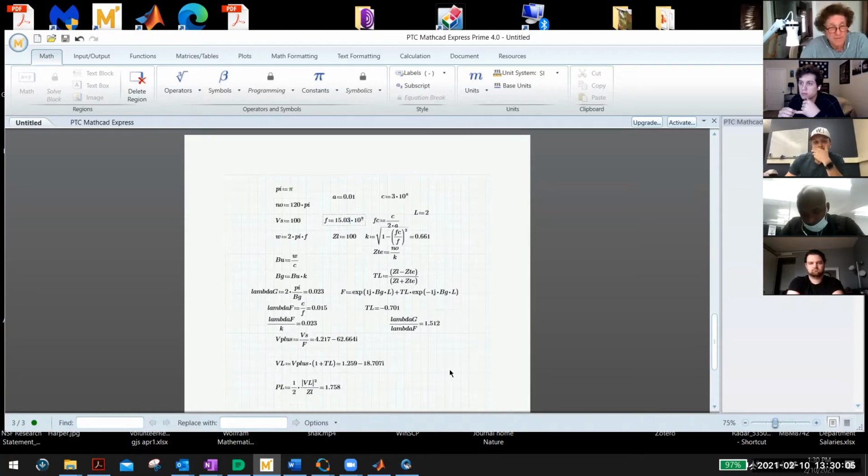Watch what happens. See how that wavelength starts getting longer and longer and longer. Now your power goes way down too, doesn't it? Look at the reflection coefficient. Now it's almost 1, right? Just about everything's reflected. That's real important to see. With me, guys?